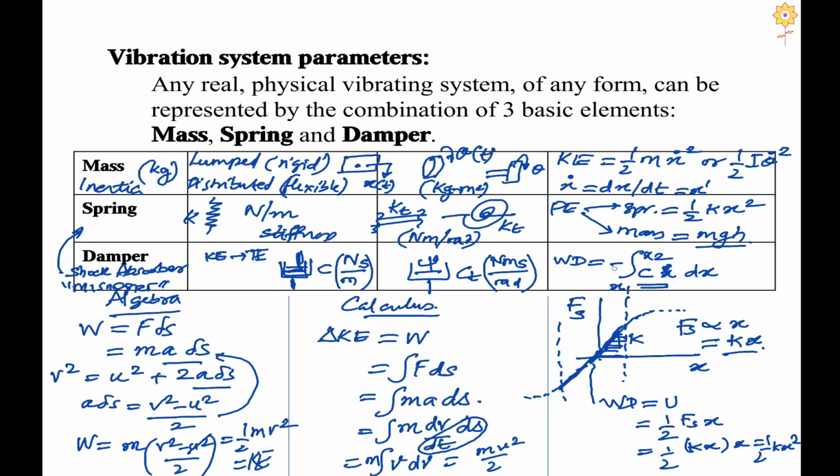So the reason why we are putting minus over here is because when the piston is at the initial position, there is an increased energy in the system compared to the final position of the piston, right? So there is a decrease in the amount of energy from the initial position to final position. So as to make the overall work done as positive, we need to associate this negative sign to this equation. So this integral term is itself negative because the energy in the initial position is more than the final position, which is giving us a negative value, multiplied by the negative value over here will give us a positive value. So this is the standard formula for the work done by the damper.